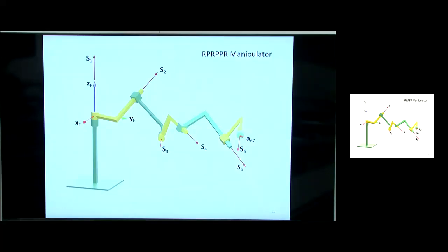So, okay, what are we going to do in the future? We're going to do 2 cases. We're finally going to get back and do a reverse analysis. We went through all of the stuff in the book, and we're doing these spherical mechanisms, and how does this come back to the reverse analysis? So we're going to do a robot such that when we give it the desired position orientation and we close the loop, we get a group 1 closed loop spatial mechanism, where in this case, I guess theta 7 is going to be known when we close the loop. And we're going to solve this one out.